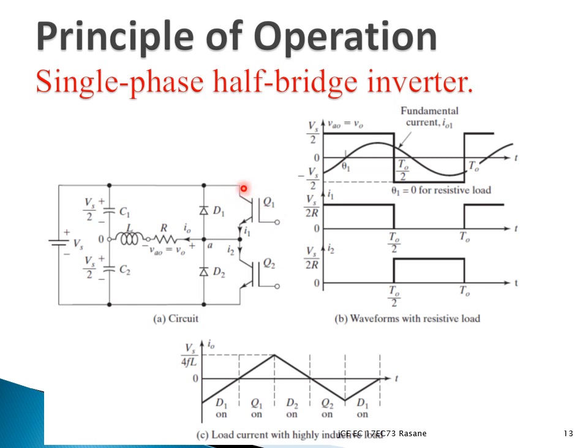What happens is this point and this point, it's turned on means connected. So this is the load. So what happens? The voltage across C1 is how much? Vs by 2. How did I get Vs by 2? This Vs gets divided between C1 and C2. So I get Vs by 2 with plus minus on top, and Vs by 2 with plus minus on top